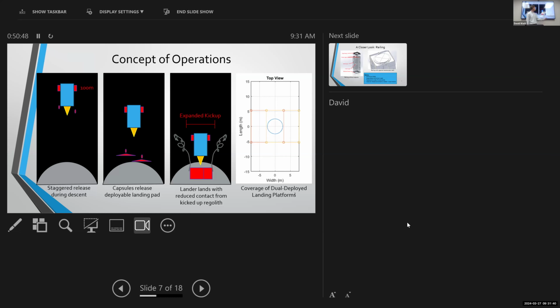That's true. So I don't know if this diagram was gone over in much detail, but that is roughly the size of the lander, and then this orange one's a tarp, this yellow one's a tarp, and remember these are being attached to the side here, and they're dropping down from there. So imagine the yellow not being there. If the lander theoretically just keeps going straight down, it's going to land way off center. So that's why we added a second one. But if you wanted more coverage in this direction, you could potentially add 2 more here. But then we were just thinking that's more possibilities of failure.